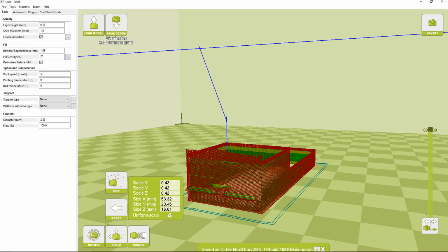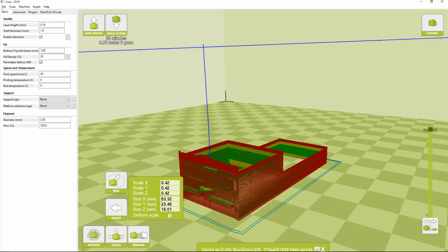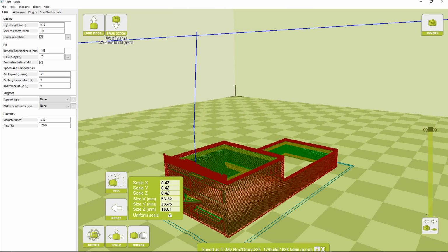And this is essentially going to establish my layer height, my speed, my temperatures. Well, actually, it's not doing temperatures. Okay, that's kind of an important thing. We'll cover that in just a second. But it's going to get the basics of that put together for me. So I know, again, my layer height, that is how many levels I have printing.